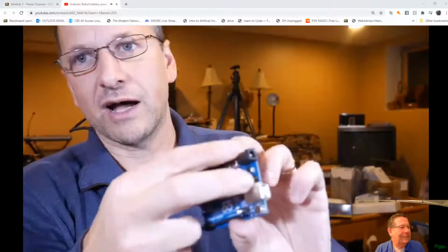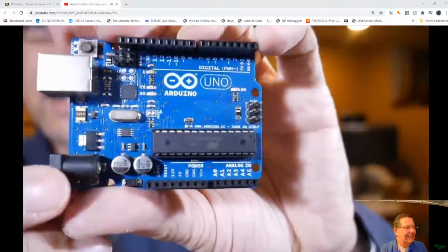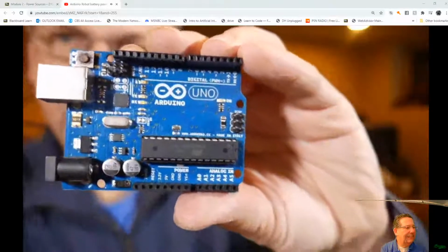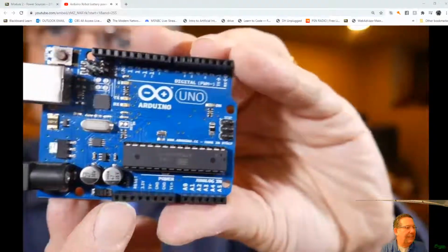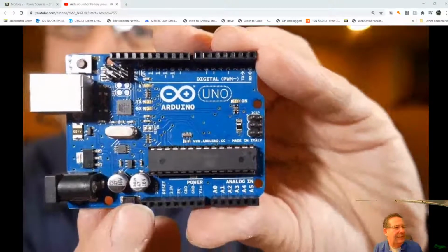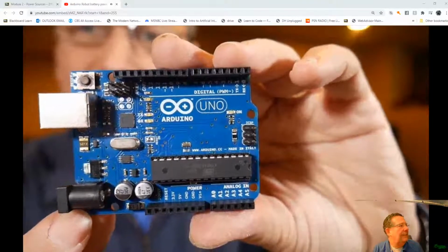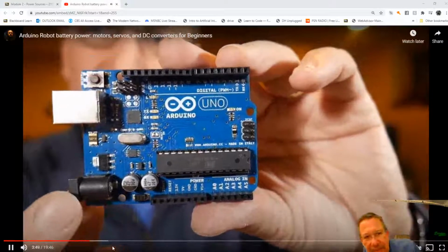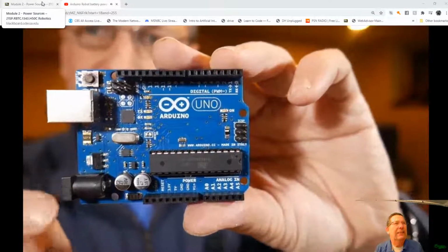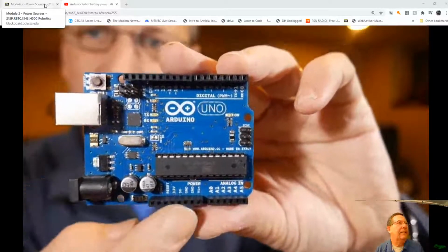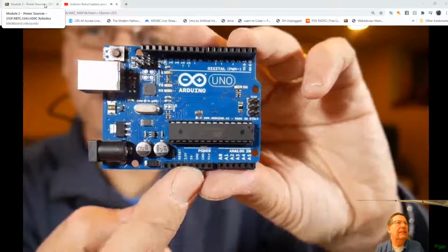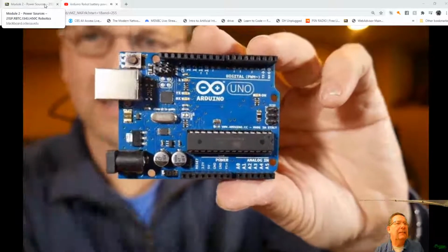So what do? First off, I should tell you, say instead of using either of these ports you want to power it directly. If you look at your Arduino carefully, on the bottom row there's going to be a V in. That's voltage in, and that can generally be between 6 and 12 volts. It's basically on the other side of the power diode and some stuff on this side, so it's a more direct route. This will generally take 6 to 12, whereas 7 to 12 on this side is the recommendation.